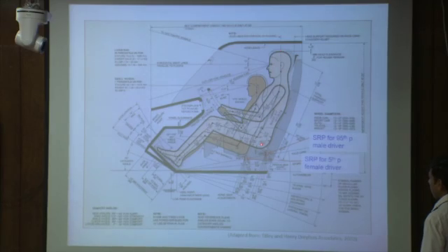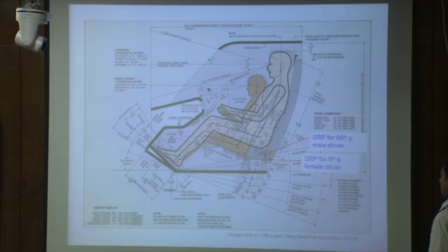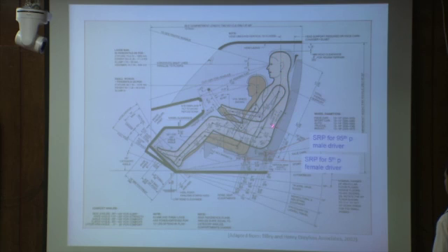Here you can see the 95th percentile driver or 5th percentile driver keeping their feet on the accelerator, and this location is the accelerator heel point, where the heel is touching. Now look at the posture. This is the typical driving posture, and this is the position of the seat.